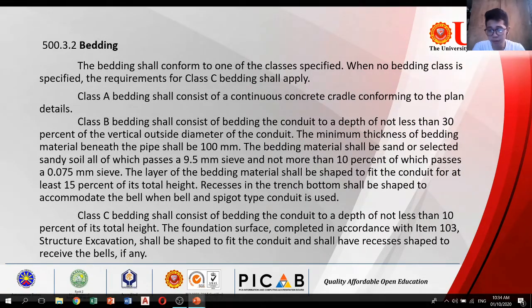So for flexible pipe, the bed shall be roughly shaped and a bedding blanket of sand or fine granular materials as specified shall be provided as follows. If the pipe corrugation depth is 10 mm, the minimum bedding depth is 25 mm; if 25 mm, 50 mm; and if 50 mm, 75 mm. You can see this in my written report. And also for the large diameter structural plate pipes, the shaped bed need not exceed the width of a bottom plate.